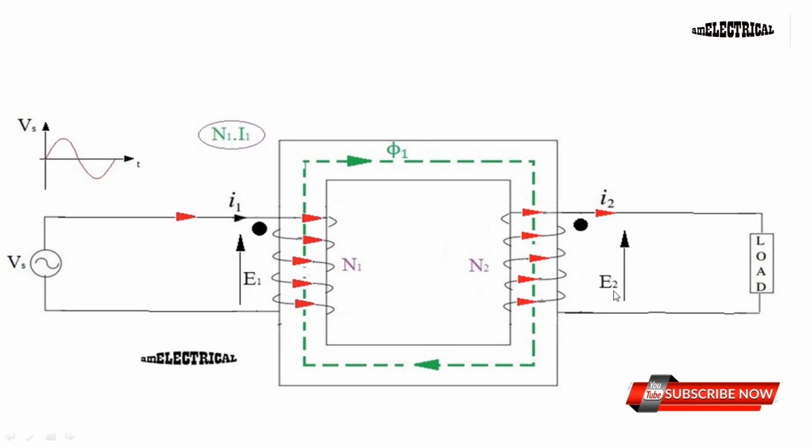As we connect the load, if the load impedance is ZL, then E2 by ZL equal to I2 amount of current starts flowing through the load via this winding of N2 number of turns. See the polarity here on primary and secondary side both. At primary, the current is entering the polarity, and at the output port, the current I2 is leaving this polarity. The term polarity is very important here, especially when we are connecting the transformers in parallel.